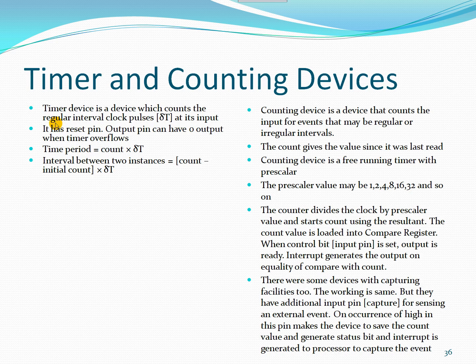Upon reaching that particular preset value, an interrupt will be given. Based upon the interrupt request, we will be doing other duties which are assigned to that particular timer. All the timer circuits will be having that input, which will be supplied by the internal oscillator of the microprocessor or microcontroller or any timer chip.